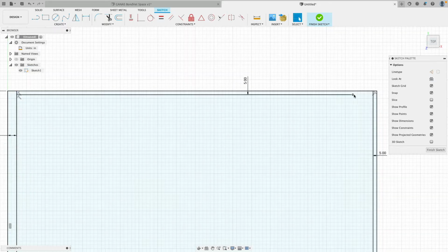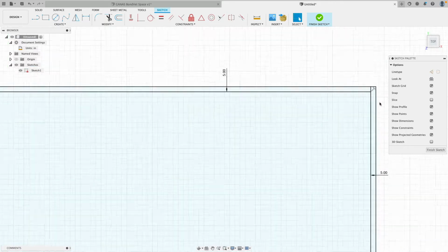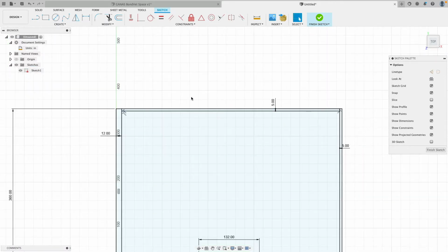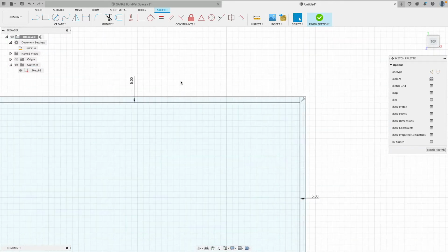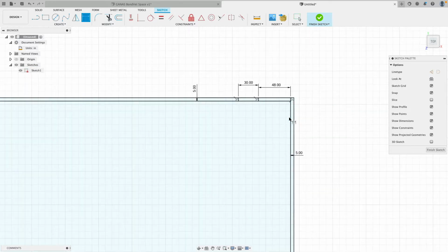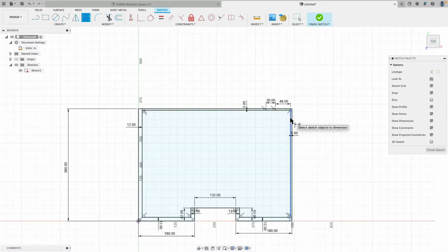And then this point here I will connect. Yep, very nice. Good. Then there will be an opening. So for the opening, I will draw already down 2 vertical lines. They're perpendicular constraint, very nice. The distance here is 30 inches for the opening, and then we set this to 48 inches away from the interior wall. Very good. Okay, very nice.